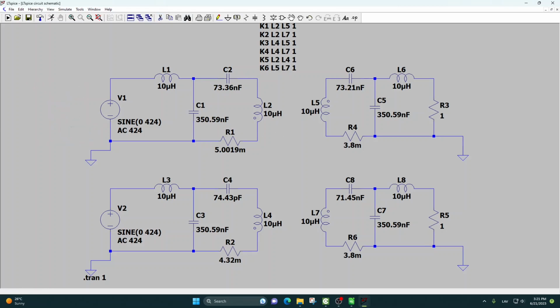The other things to keep in mind are actually two. First of all, for coils, I would suggest to define the coil self-inductance already right now. The whole point of the integration between LTspice and CENOS is to calculate iteratively these values, such as coupling coefficients and also self-inductances of the coils. But I would really suggest to at least input some kind of estimation of what it could be, because that will help CENOS with the calculation convergence, and it will simply speed up the calculation.